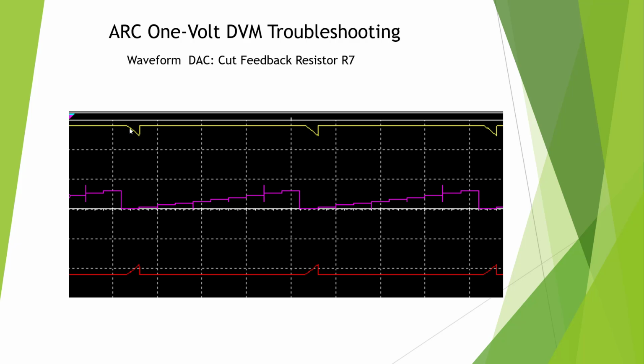And the yellow one here is after it goes to the inverting 1-to-1 op amp, it goes positive. So here's our first signal, and here's the output, which we'd be looking at as our test point 1. And we see here at our virtual ground, we're getting a signal from the resistor pack.